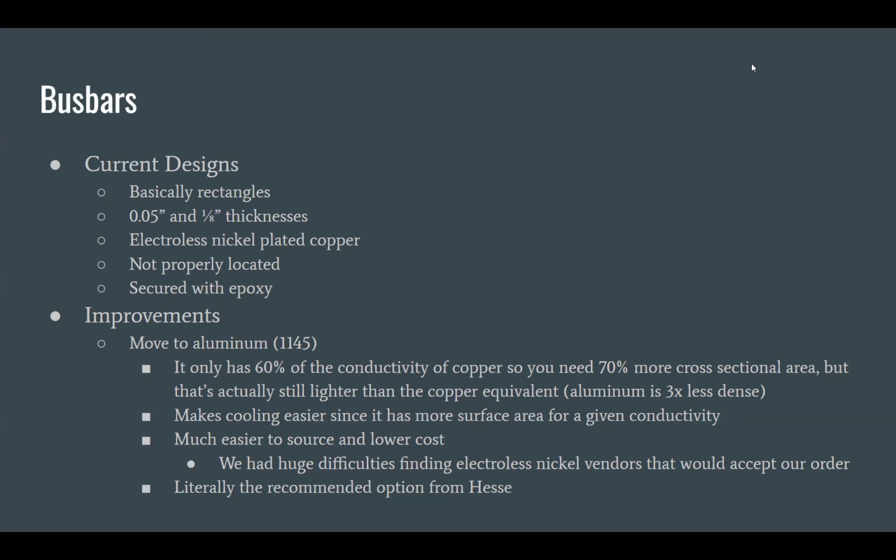That means you could make a lighter battery pack too, which is super cool. It would be cheaper. Yeah, so it would be cheaper and lighter, and that's great. But obviously the downside that Joshua highlighted really well is the fact that you still would need to go up by 60 or 70% in your cross-sectional area, which means that your battery pack is getting bigger volume-wise. And if you don't necessarily have the space in there, then that can become a big constraining factor.